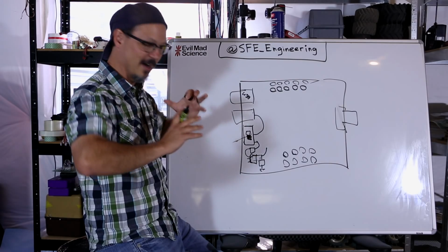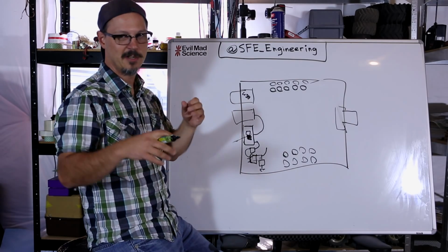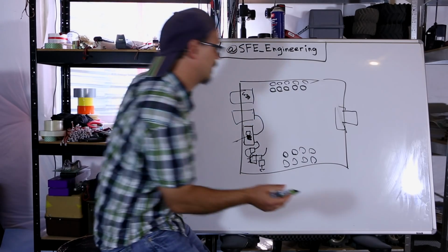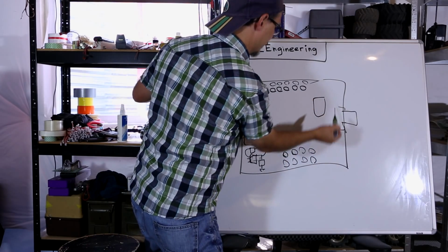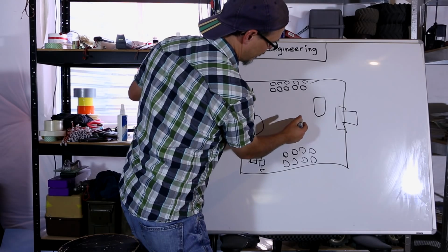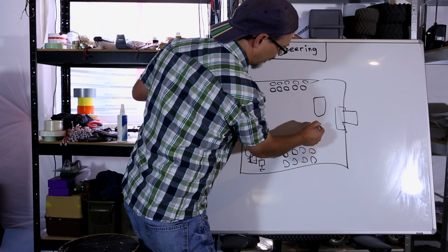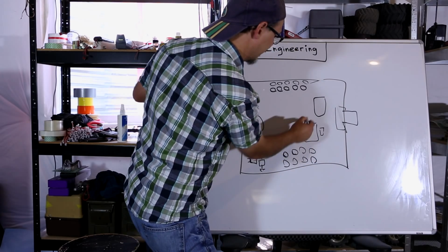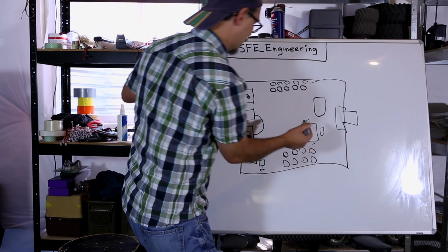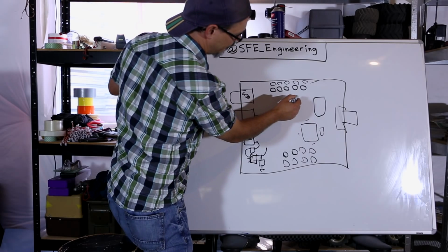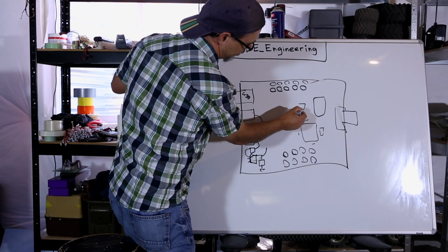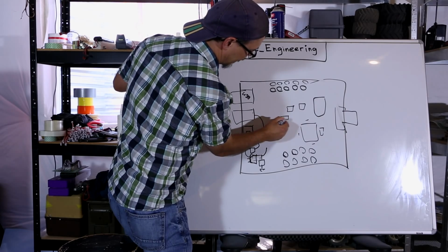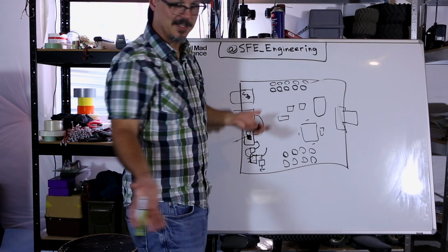Now, your sections, right, you're going to have a microcontroller section. You're going to have, let's say, sensors, right? If I had an RF link, I would probably keep an RF module over here. I might put my microcontroller here and maybe orient it so the crystal was nearby, with a couple of caps that decouple. And then I might put sensors here, maybe a multiplexer. I'm making this up as I go, right?